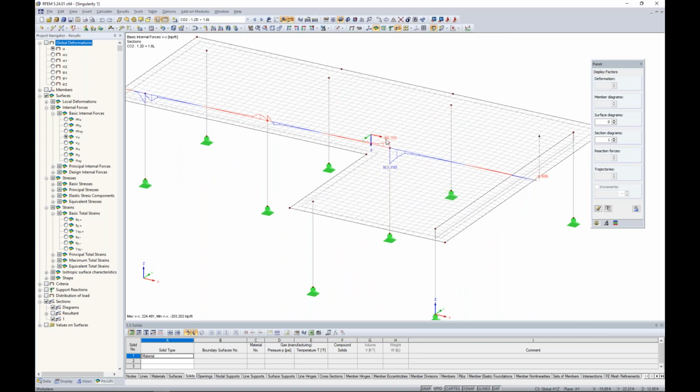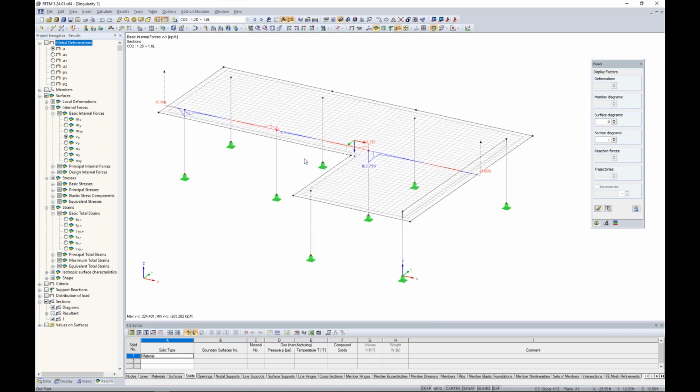We're seeing from negative 66 kips clear up to 163 kips, all at this single point location. So there's got to be a better way to distribute the forces over that entire portion where the column's framing in, because we know in real life it's not represented by this single line element.